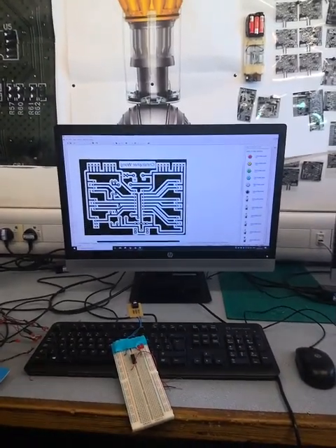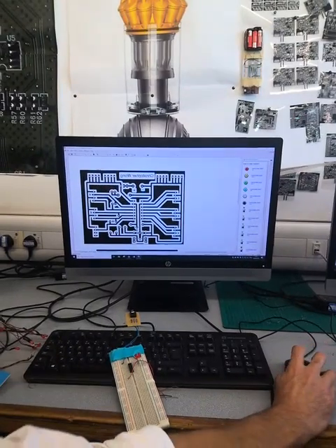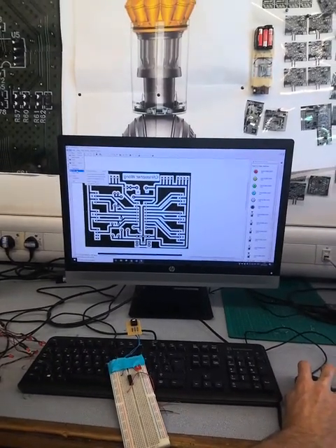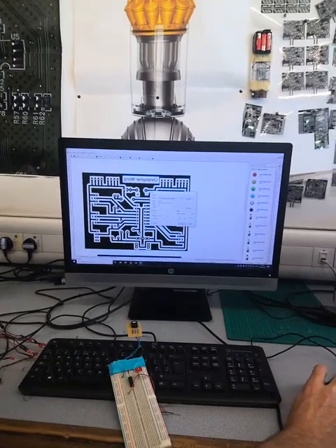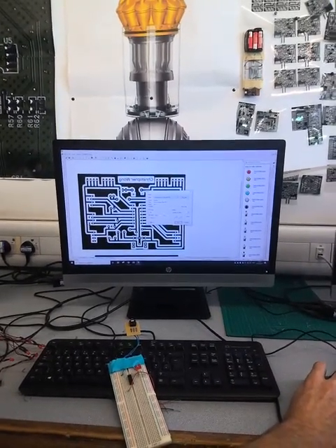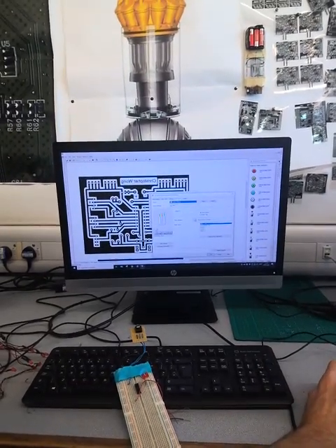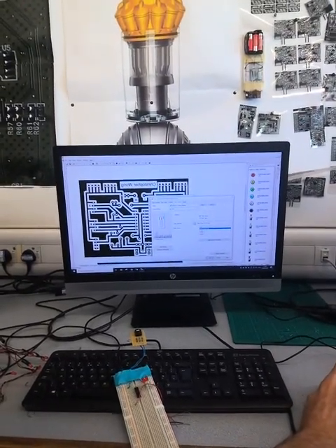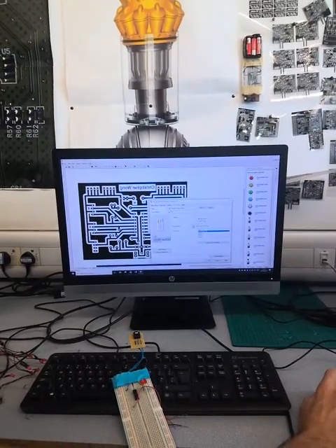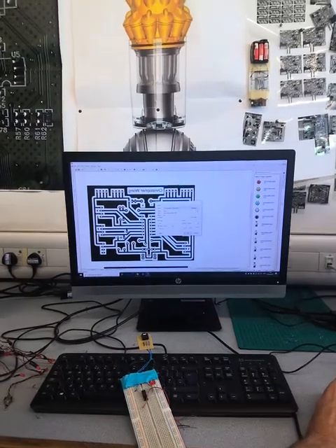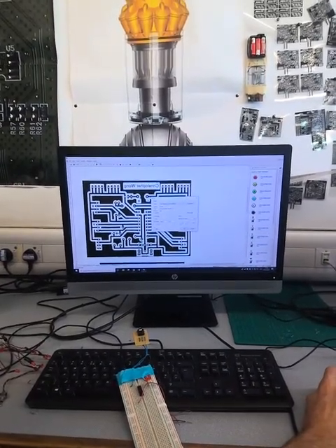How do we send it to the printer? Well, we go to File, we go to Print, Current Design. When we go to Print Current Design, we go to Properties. And on Properties, we go to Paper Source. And we must select the multi-purpose tray, okay? It's really important.